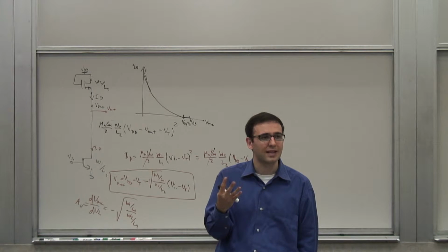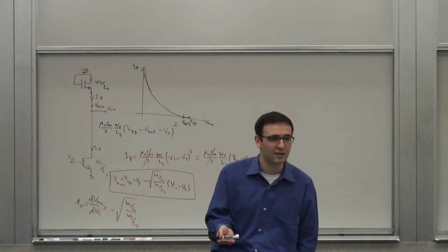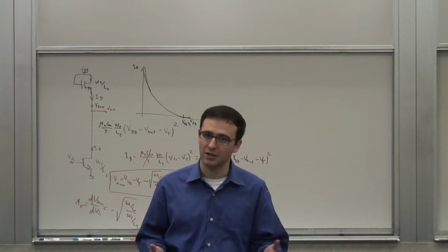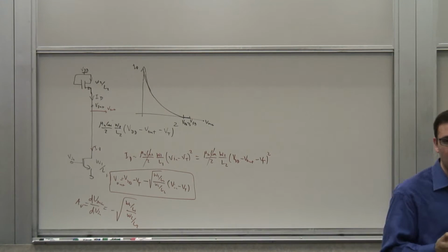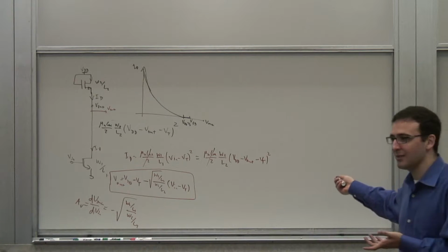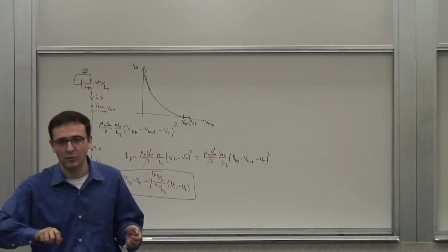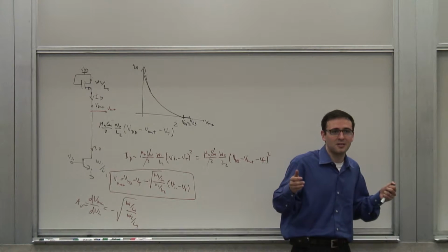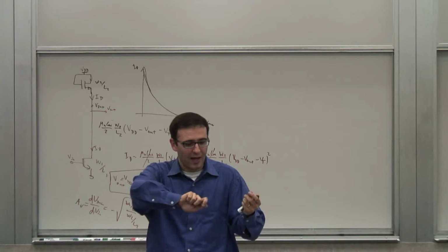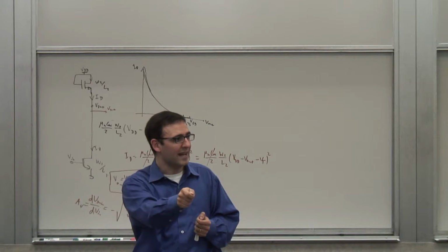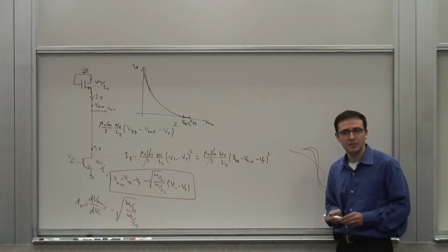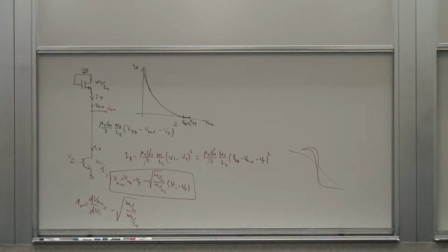The rest, if you listen to it, actually you hear it. Sometimes you do that intentionally. For instance, in a guitar amplifier, if you're making a pedal or something like that, there are all sorts of distortions you introduce because they make it sound richer in terms of the harmonic content. So one of the basic things that you can have in a guitar amplifier is the nonlinearity. I don't know if you've played with an electric guitar amplifier or not. Does anyone play with that? All right, well, good. You have this knob that you turn, and it's called gain. So what you do, you're increasing the gain. In effect, you're making the transfer function steeper and steeper as you do that. And you hear this kind of distorted sound of the electric guitar as opposed to the smooth sound of the basic acoustic or basic string.